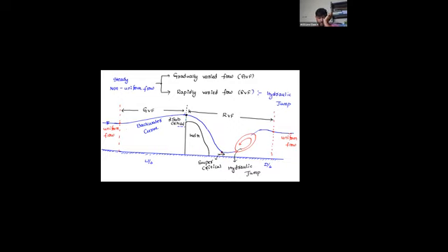Now again, as the water level rises and rises, again it reaches the final position. And here the depth is going to be large and the velocity is going to be less. This is again subcritical. I hope you understood the definitions. So whenever the flow has a larger depth with a lesser velocity, we call it subcritical flow. Flow with a smaller depth and a larger velocity, we call a supercritical flow.